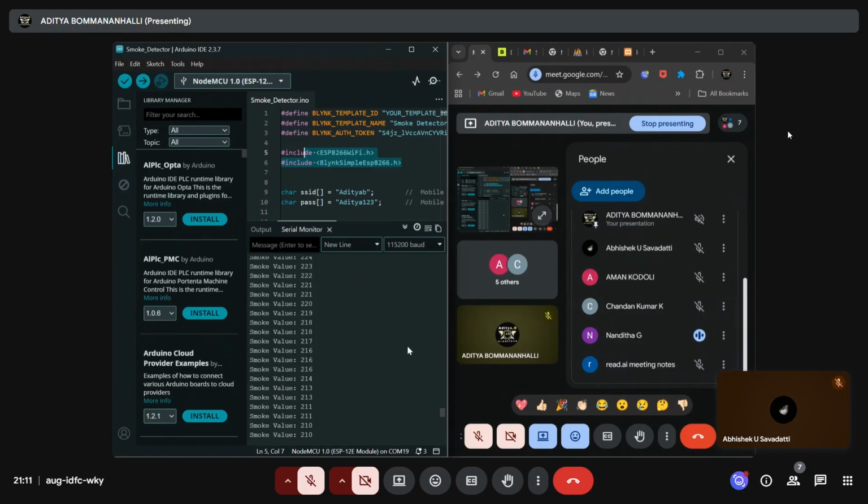So did you face any false alerts in your project? When the MQ sensor heats more, sometimes it gives values like 400, 500. So we researched about it. It tells that the MQ sensor is made of a coil inside it which will be heated, so basically it will give false information sometimes if the system overheats.